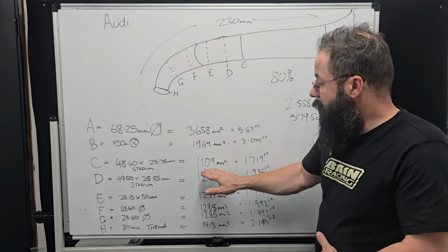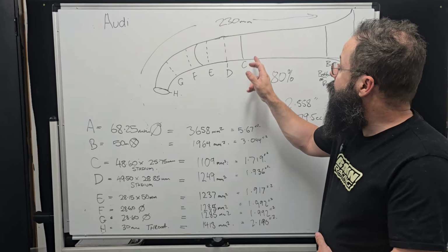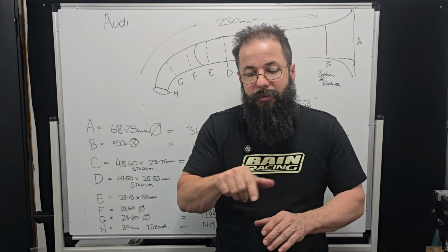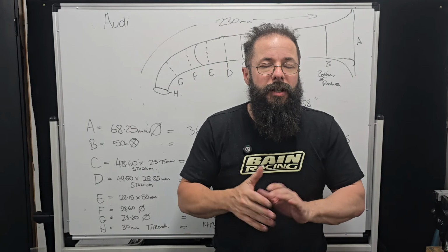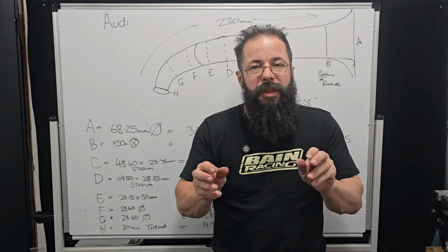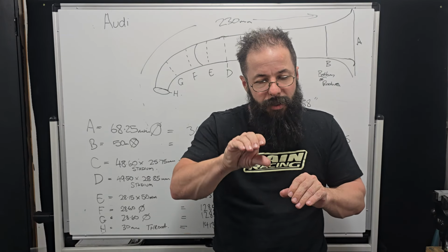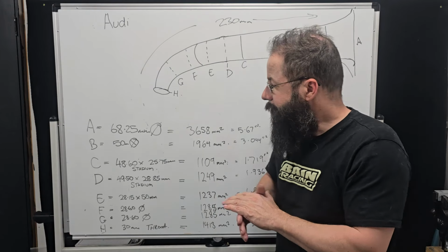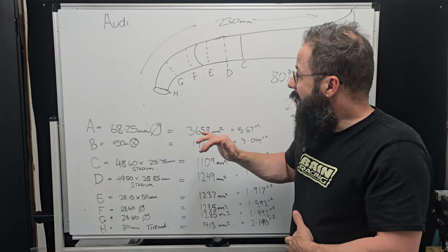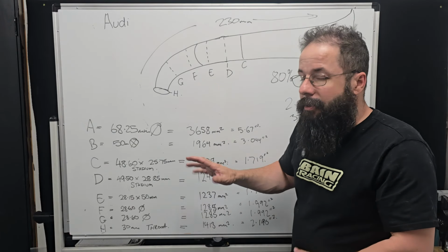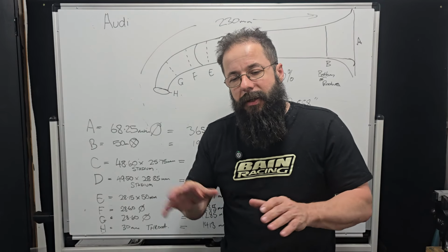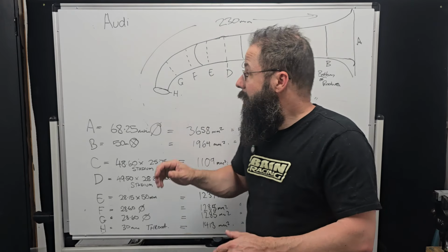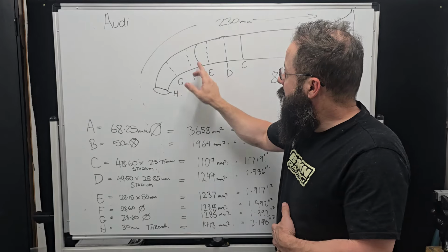I'm going to try and pinch this out in the manifold because it's got a really, really tight spot in the manifold itself, just where the injector is. I'm going to move the walls out just a little bit, but it's thin. I can't touch the floor or roof because it actually pinches down and pinches in a little bit. But we'll leave that, or we'll take it to 1150 and probably leave it at that. That'll get us down to about that 645 maybe. But this is the area we need to work.